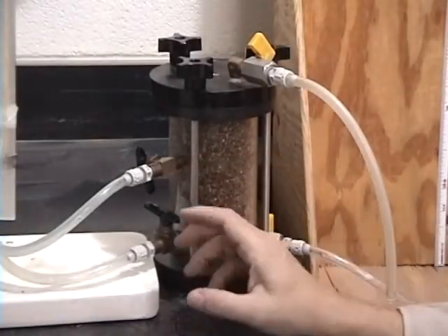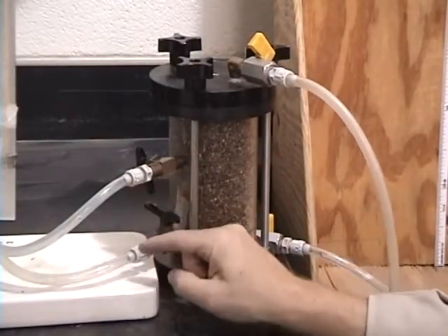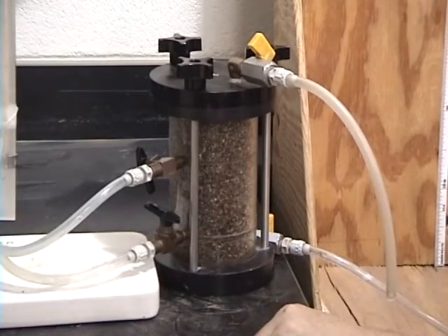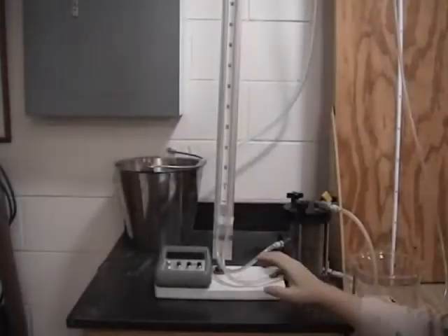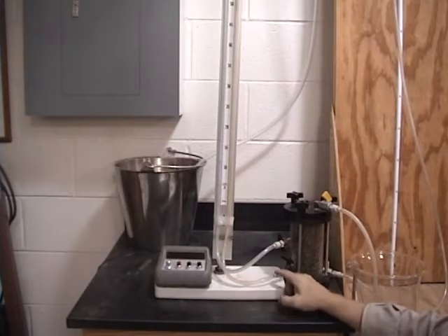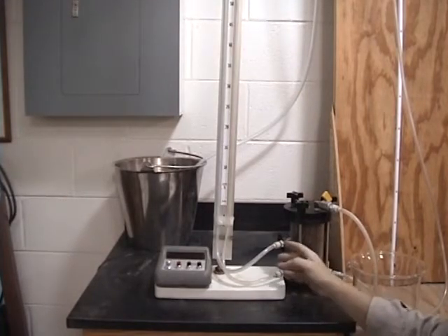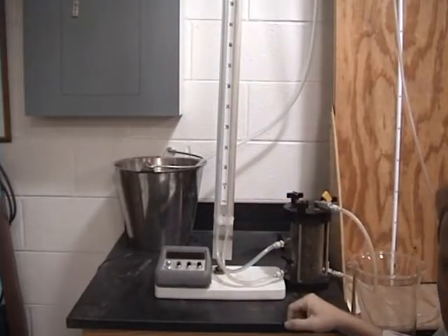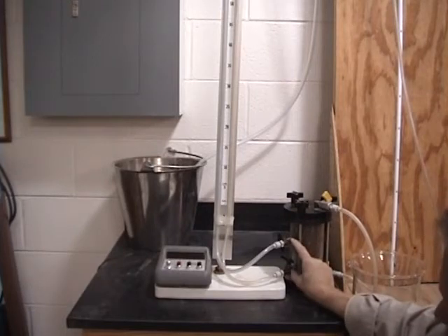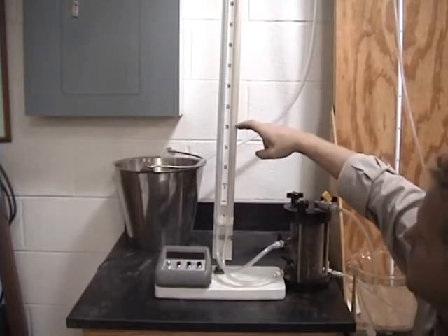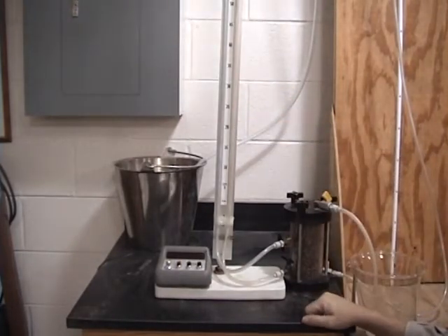These ports are hooked up to a manometer. That's what these tubes go to. Let's take a little bit of a closer look at the manometer. So here's the manometer. These are my tubes coming out of the ports. And as we permeate water through this specimen, the water level will rise some given height in each of these tubes. We're going to measure the head loss across these 2 ports. And that head loss will be basically the difference in height of the water level between the 2 tubes. That head loss we'll define as delta H.